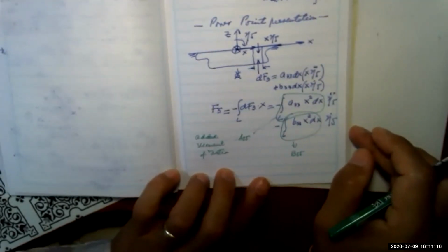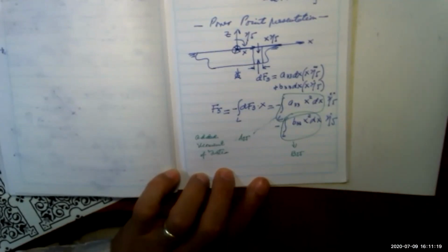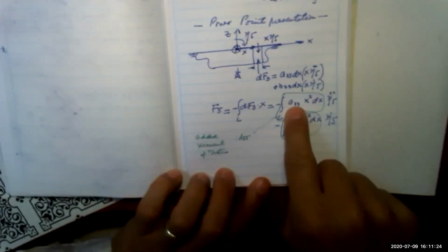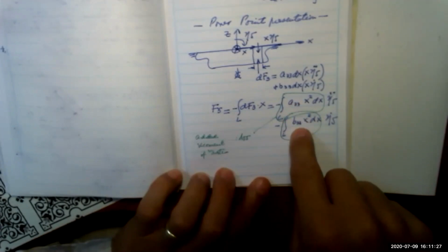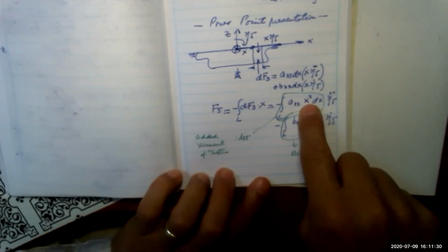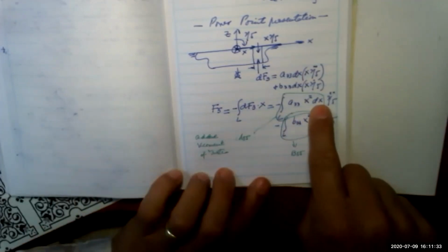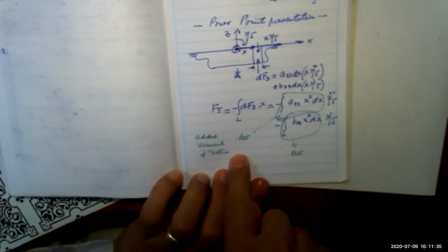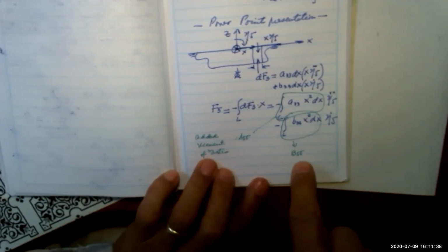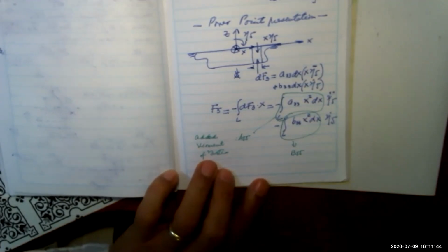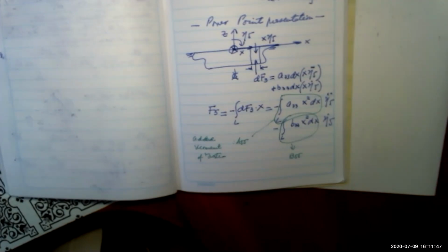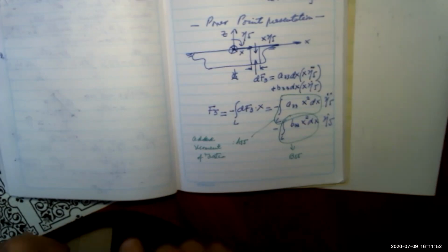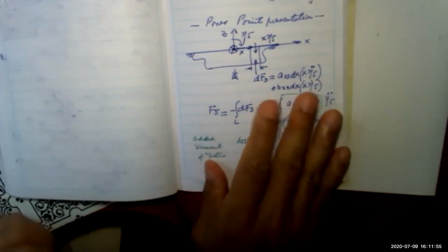Okay? People, are you with me? Okay. Yes. So you have A33, B33, and you multiply that by x squared and integrate it along the length of the ship, and you will have the added moment of inertia. You do the same thing with B33, and you will have the damping moment for pitch calculations. Okay? So that was one thing.